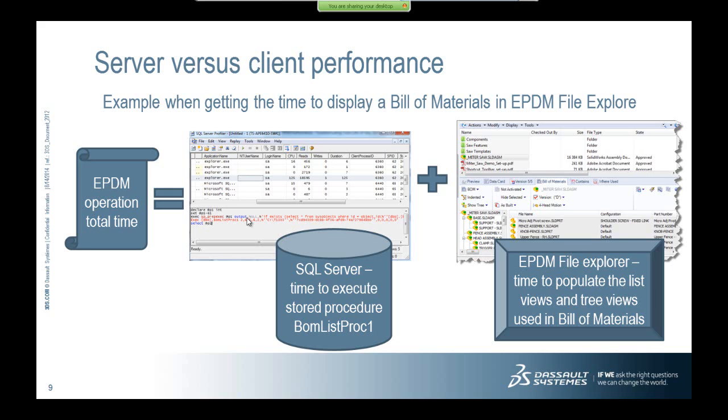You can use a tool like SQL Server Profiler to capture all the SQL statements. You can identify here in the application name ExplorerX, which is the PDM file explorer, and you will see here in a column the duration of your operation, and the SQL statement will look like this.